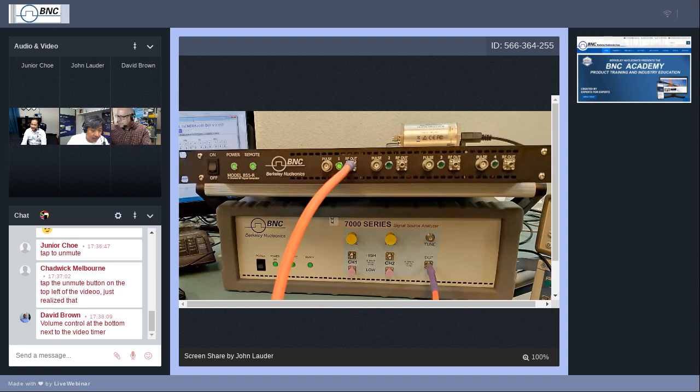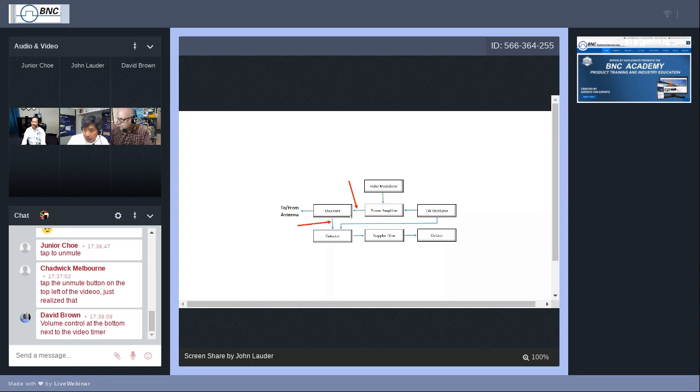In the real world, as was mentioned earlier, for a pulse measurement in general, you measure after the power amplifier, where the output will be pulsed RF, and after the duplexer, or in most cases, after the receiver. So going back to my signal gen.